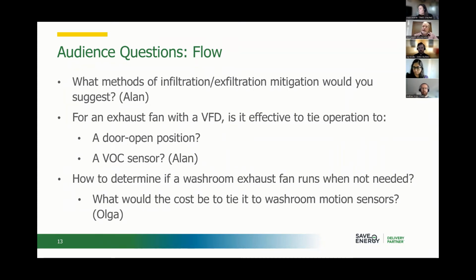One of the things that I highly recommend people do in their systems is have a very good idea of what the pressure should be throughout their system. So when you've got a system that's brand new, for a particular flow rate, it's tested, you go through your system and you go, okay, I know what the pressure is here and here and here and here. And then later on, as this system gets used and there's maybe erosion issues or wear issues or buildup issues and so forth, then you can see how that changes over time. So I'm not sure if I'm down the right path with Alan's question.